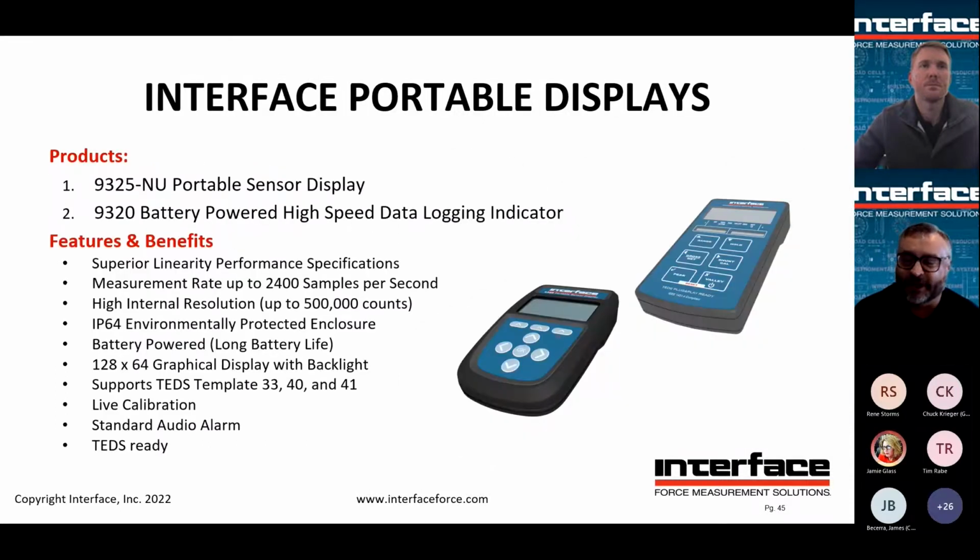These are some handheld displays. We actually have a number of customers who are interested in walking around the plant and grabbing weights from certain things. Imagine they have some gas cylinders here and there, and they want to plug in, take a weight, and then walk away. You can do that with the portable handheld display. And if you have TEDs, it'll self calibrate every time you attach it to a new load cell.